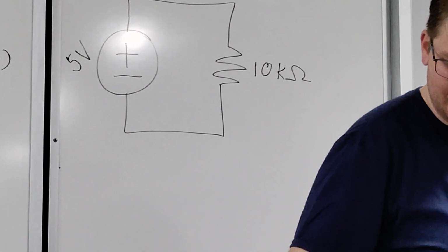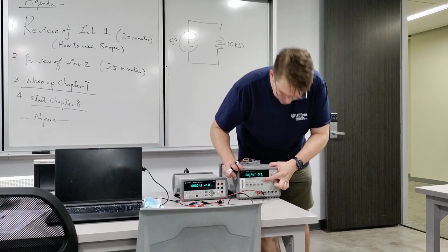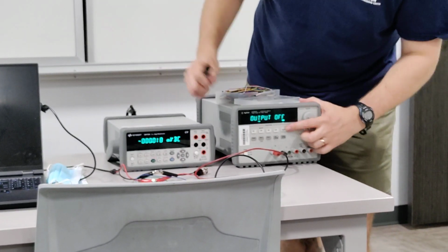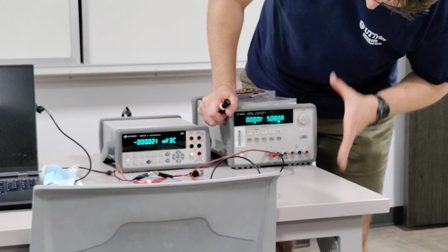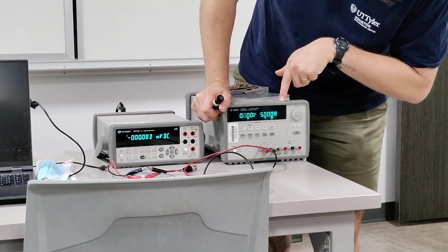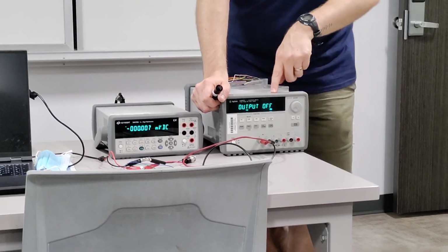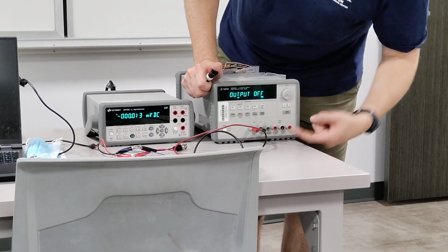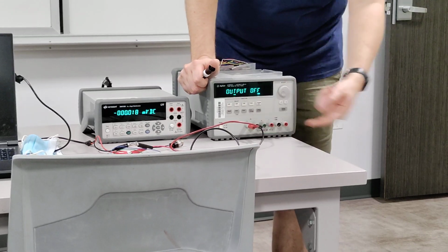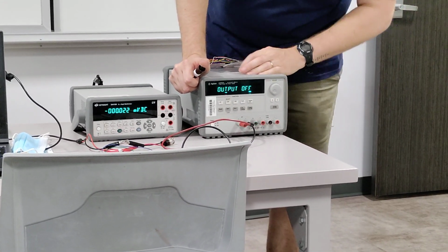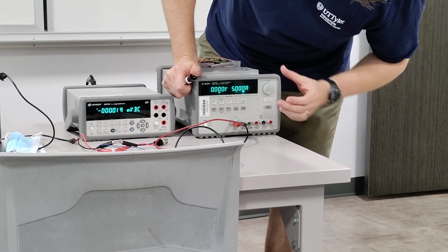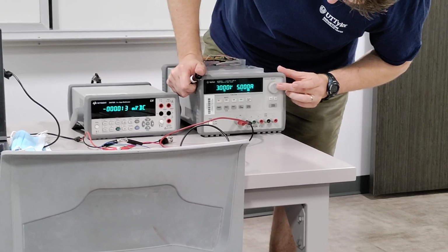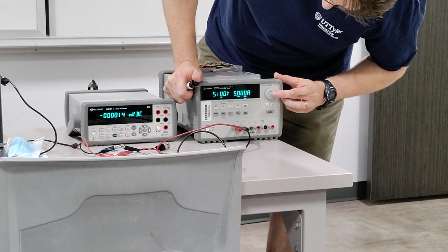There's a very important setting on this guy. If you click display limits in the top right, right now it says output off because the output is off. If you hit display limit, it gives you this screen. It says 0 volts and 0 amps because it's providing 0 volts and 0 amps. It also says plus 6 volts to tell you that you're currently adjusting the plus 6 volt channel limits. I can now change that number with this knob. If I want this to be 5 volts, I set that to 5.